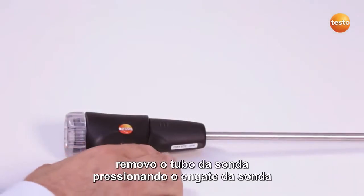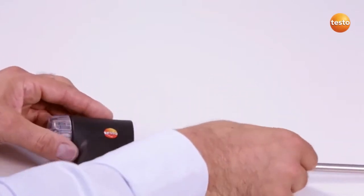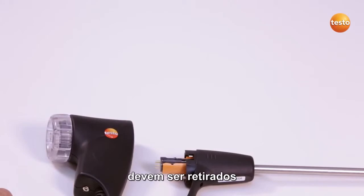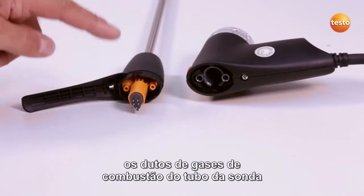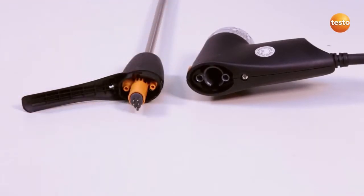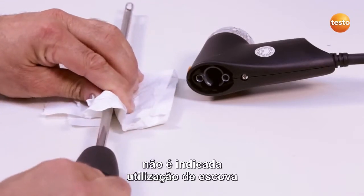I remove the probe shaft by pressing the probe release. I can then remove the probe. For probe shafts with a pre-filter, this must be unscrewed. The flue gas ducts in the probe shaft and the probe handle can be cleaned out using compressed air. External cleaning is done with a cloth. Brushes should not be used.